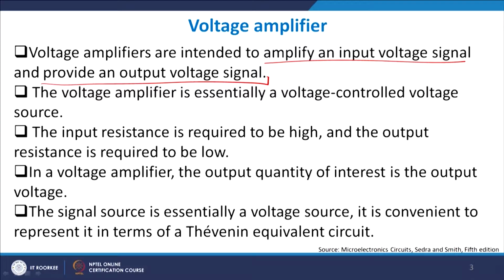At this stage at least we are not talking about a change in the frequency of the input source. We are keeping the input stable at, say, omega, and we are trying to find out the variation in the peak to peak signal of the output with respect to A and beta. A is the feed forward amplification factor and beta is the feedback network factor.